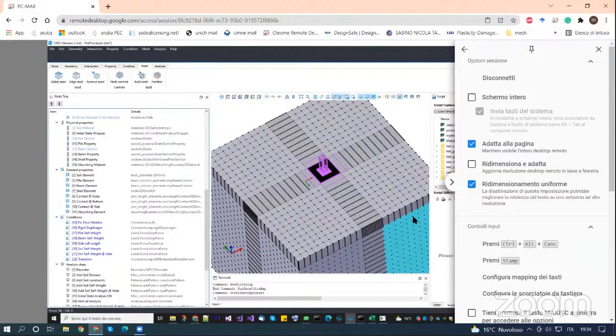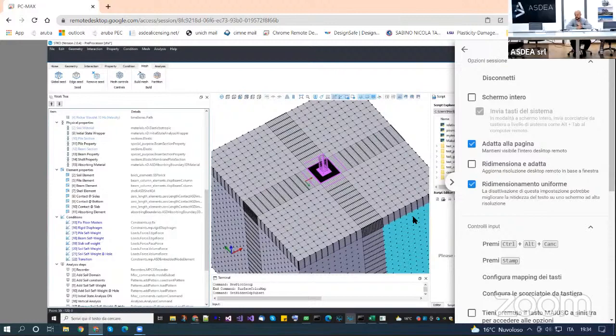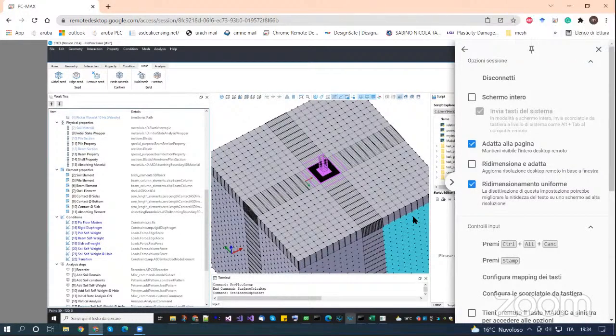You select the range of frequency that you want to represent properly, but the question is what happens if you do not represent the other frequencies properly. It should not be a problem, but you can use the benchmark examples in 2D to understand exactly what happens. If my mesh is too large for that frequency, is it going to create a problem, or does it just dissipate some of that? The problem is that I'm still studying this topic, so you need to use this benchmark to understand what happens.